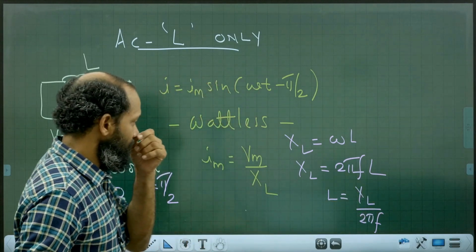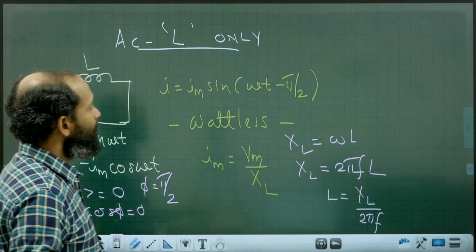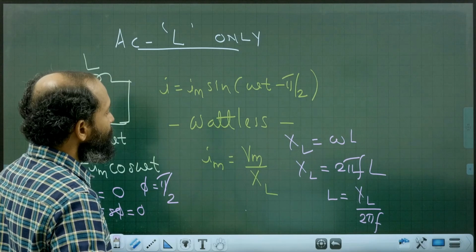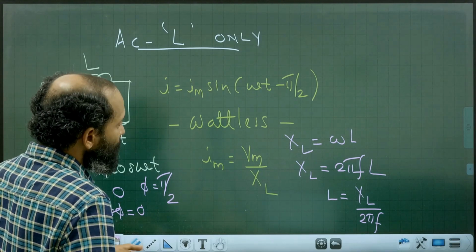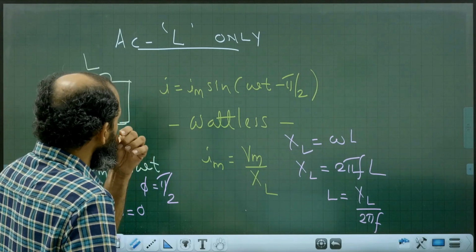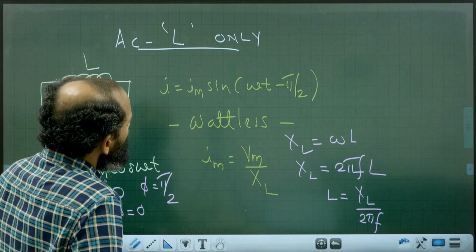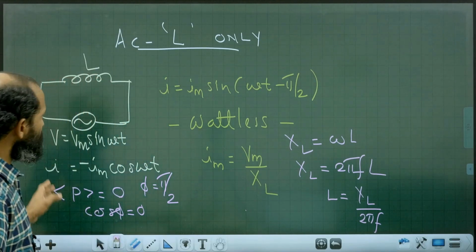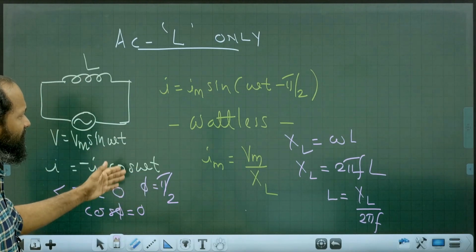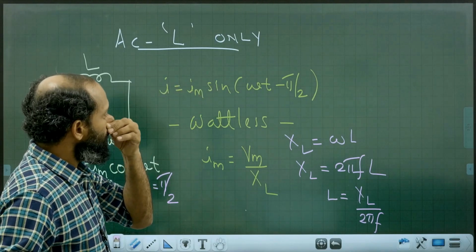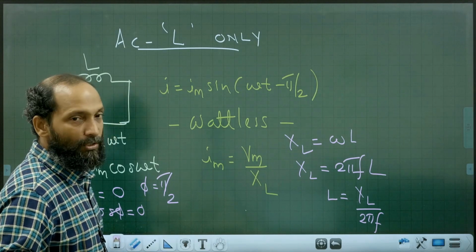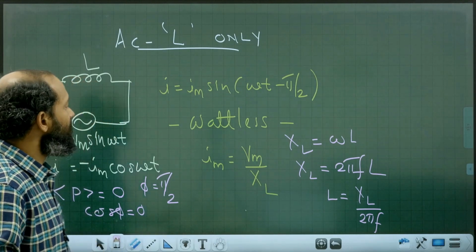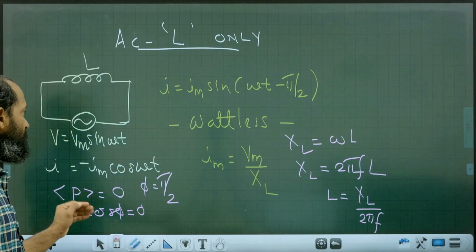That's very important. Inductance is the property due to which a coil has the ability to oppose any growth or decay of current. That also we have learned in the chapter electromagnetic induction. So this KVL equation and also this phase angle, current lagging behind voltage, are important. XL equal to L omega, inductive reactance, all this is important. Average power consumed is 0.